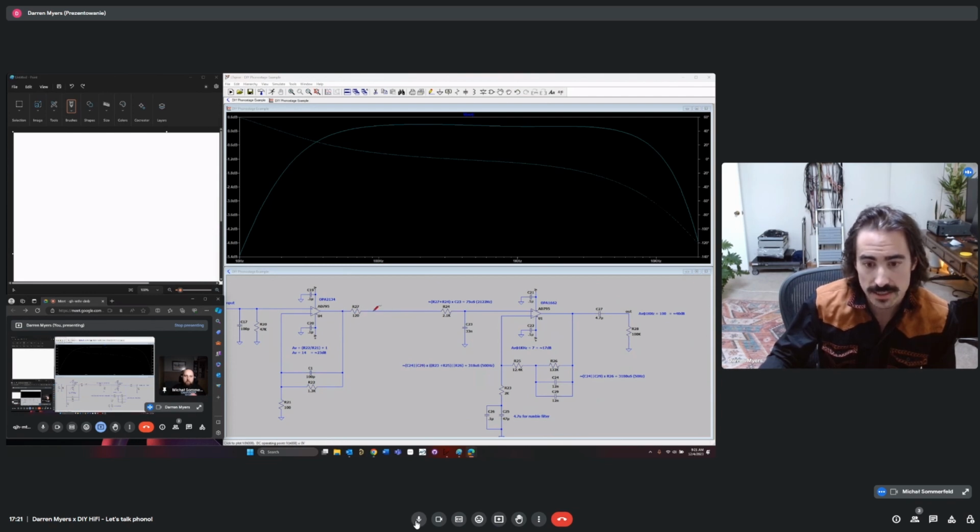What that does is it isolates the trace capacitance, which is this line right here. And then I get to move R24 close to the input of U1, and that reduces the capacitance that's seen here. And so you reduce the parasitic RC because we're coming from a higher source impedance now.